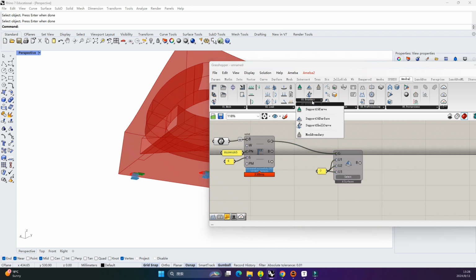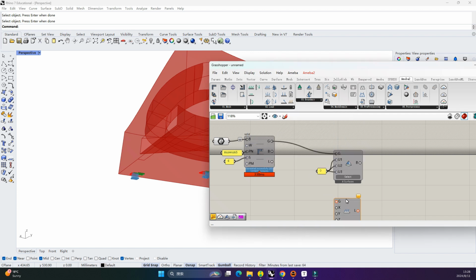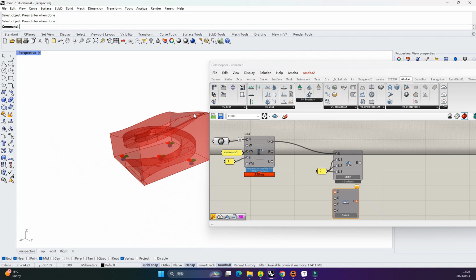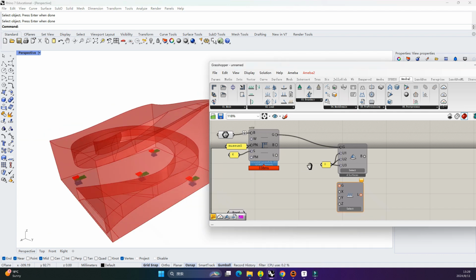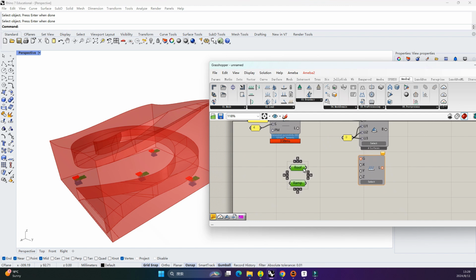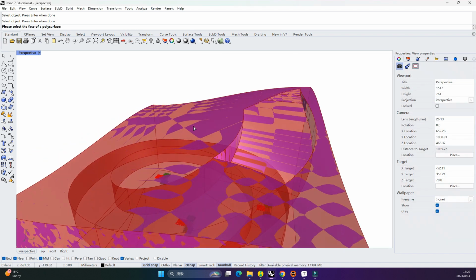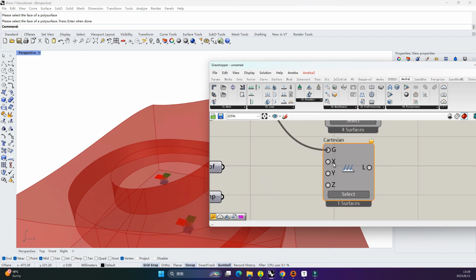And next we can define the load. The load should be a 3D surface load. To simplify, we can use the same number for the roof and the ramp, so we can join input G. We can give the roof first, maybe Z. We can give the -1 here.